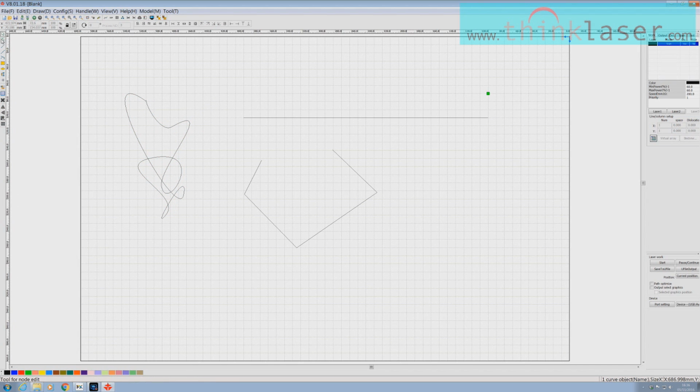As soon as you select the node tool, if you watch down at the bottom of this toolbar here, you'll see you get a secondary toolbar appear. Now these are various selections that go along with the node tool. And if I go to the top of that toolbar just there, look, you can see I've got a little movement cross.